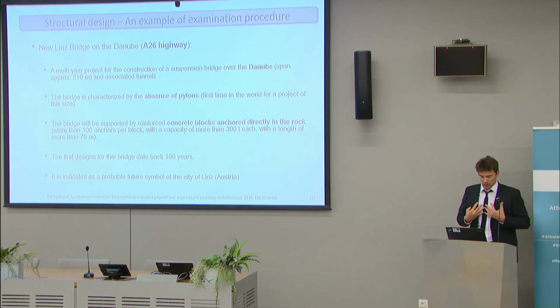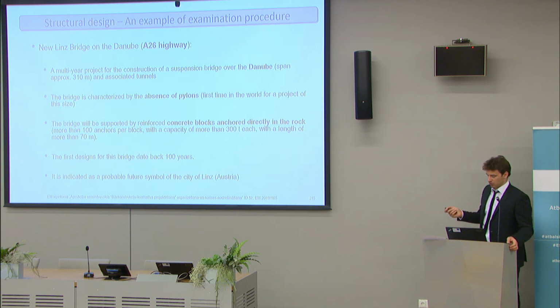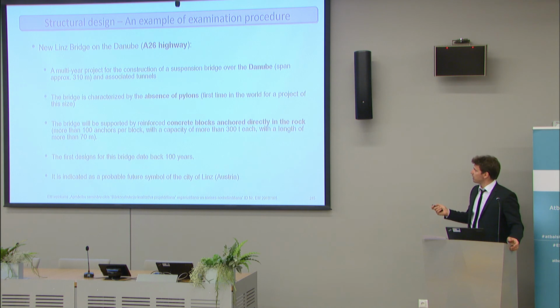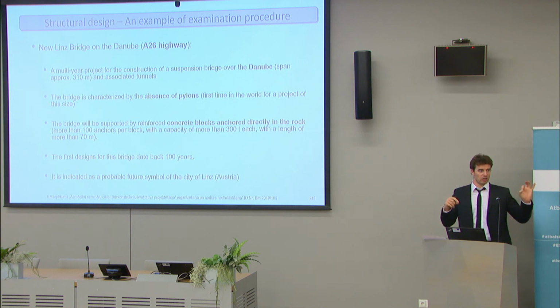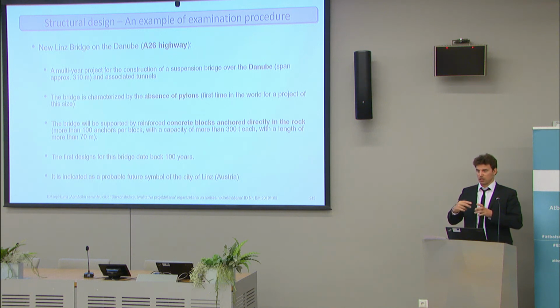But what I am responsible for is making these concrete blocks that are anchored directly in the rock. And as I was telling you before, you don't have much space. Each anchor's borehole is 210 millimeters wide, and you have just 70 centimeters from the next one. First, they don't want one to touch the other. But second, and it's very important, at the end of the anchorage, in the zone where the anchorage is stressed, they need at least 1 meter from the next one.